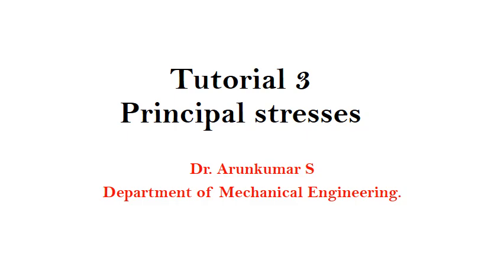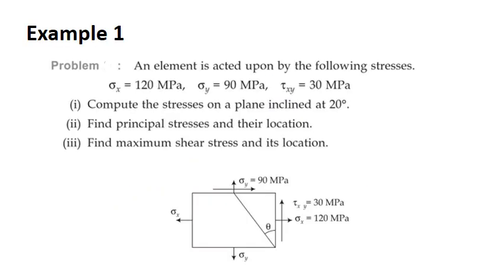So today we will have another tutorial session on the principal stresses. So the first problem. Here is a small element chosen from a component. The components of the stress acting on the element are given. The X component is 120 MPa, Y component is 90 MPa, and shear component is 30 MPa.